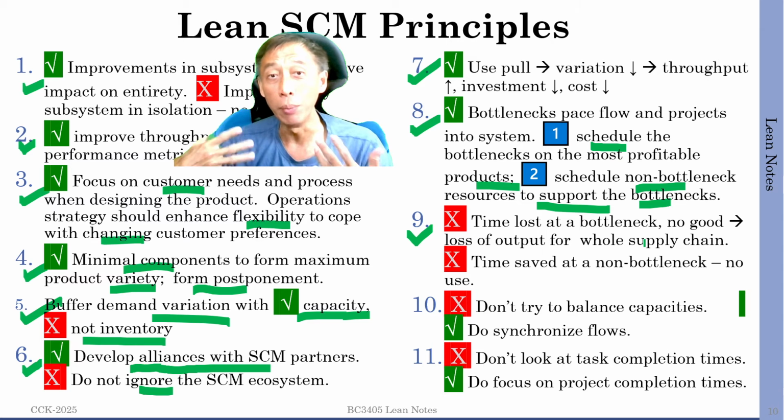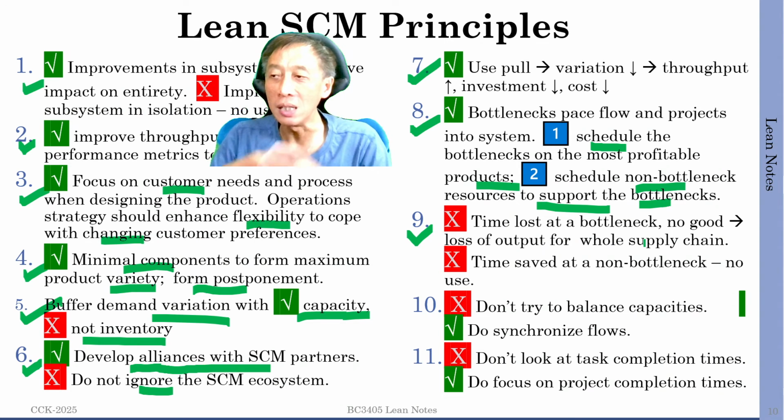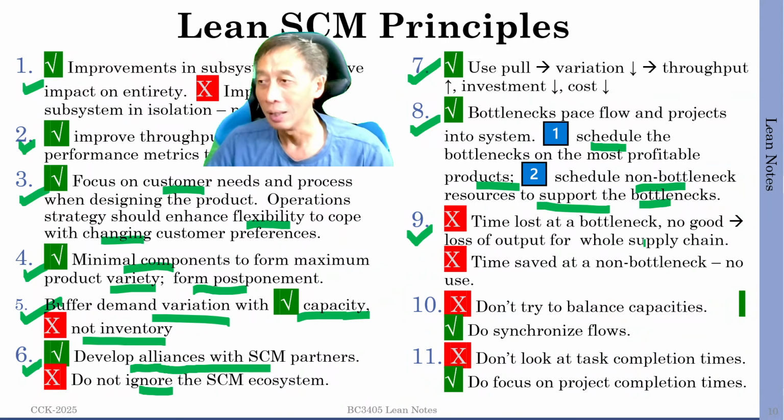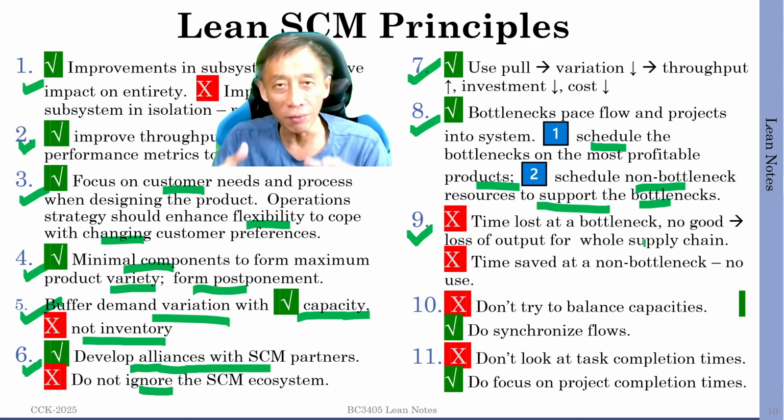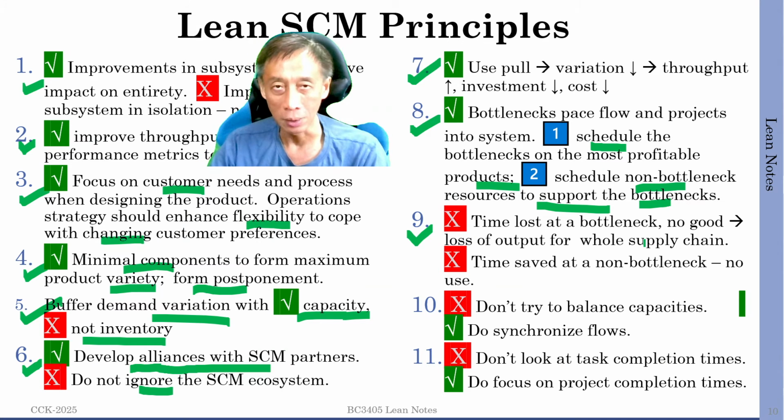You incur breaks, correct? Yeah, you have longer setup time. You have breaks. You have excessive maintenance. You didn't supply the raw material, so that bottleneck is forced to stop because it's starved. It doesn't have raw material, so what do you want me to do? I'm working on nothing, right? So you didn't pay enough attention to feed the bottleneck. So all these are time loss. That's always not good. Time saved, right?